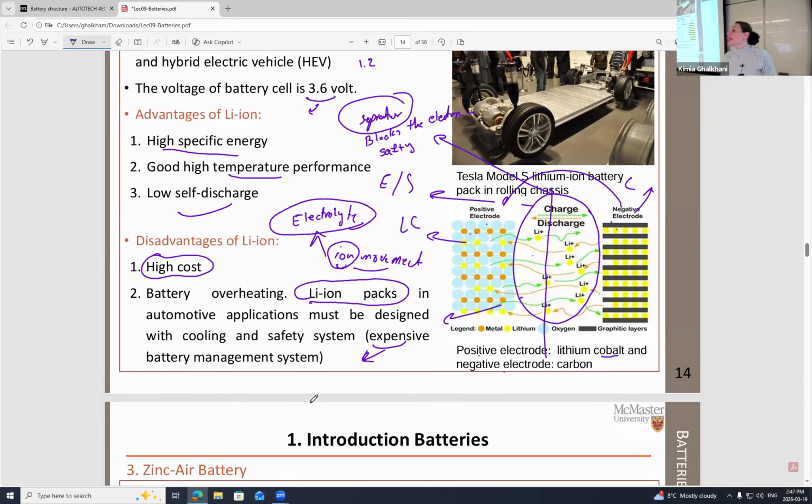And of course, in addition to that, I said it before, I'm gonna bring it up again, the battery management system, which is like a control unit in order to be able to report or maintain the state of health, state of charge, state of discharge, and all different characteristics of the battery under a certain monitor, or maybe I would say LCD sometimes. Sometimes it will be sent to the dash if it is hooked inside the vehicle.